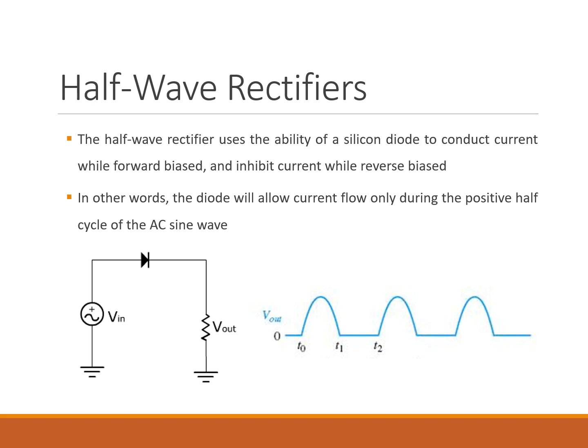Let's go ahead and break down the waveform. So here's what happens to the AC waveform. During the positive half cycle of the AC cycle, the diode is forward biased, current flows to the load, but during the negative half, the diode is reverse biased, so that means current is blocked, so nothing conducts on the reverse bias. And the output is a series of positive pulses, and this is your half wave DC.